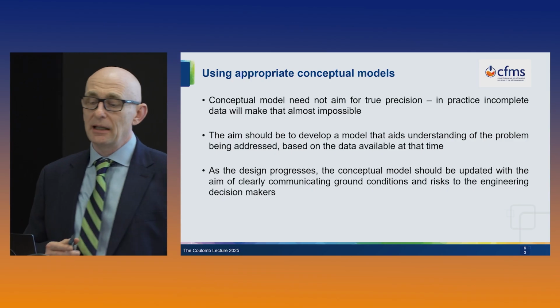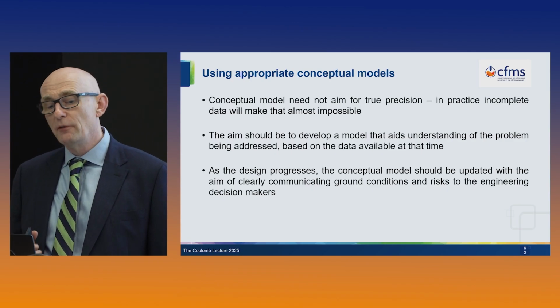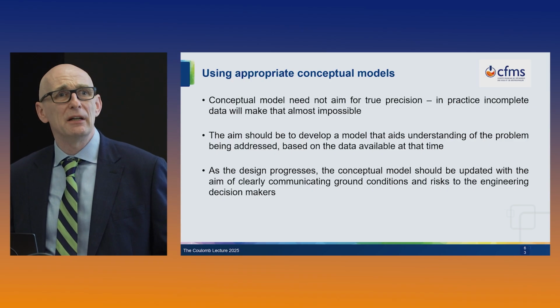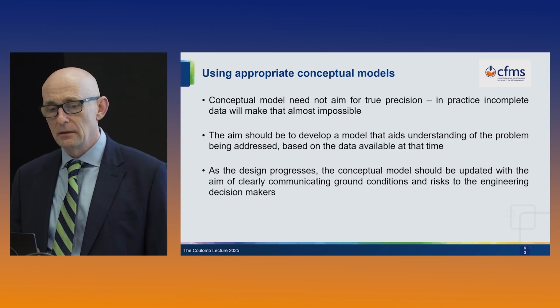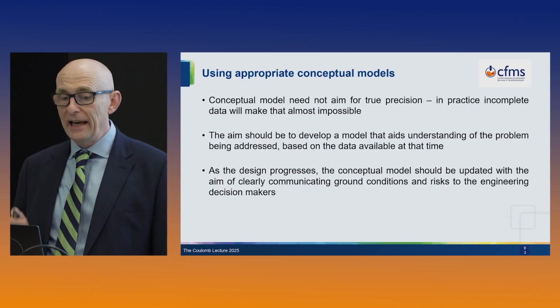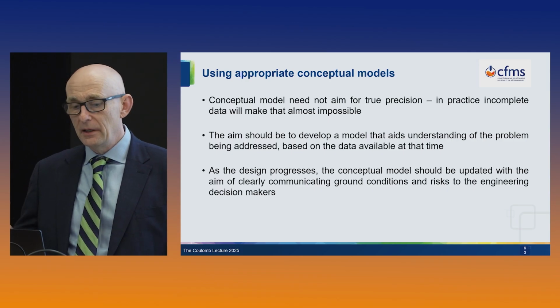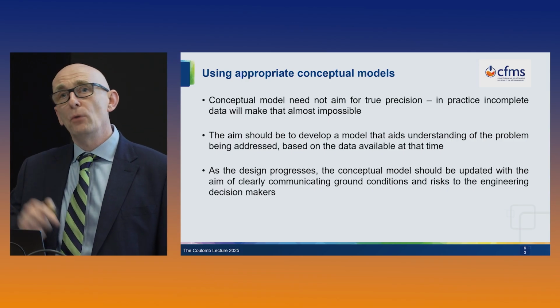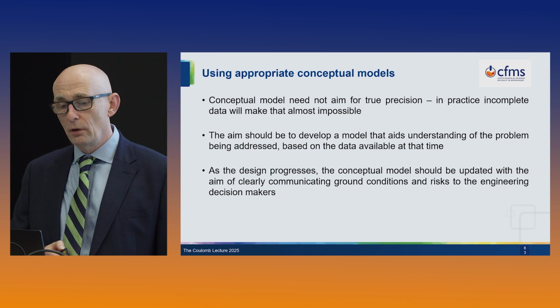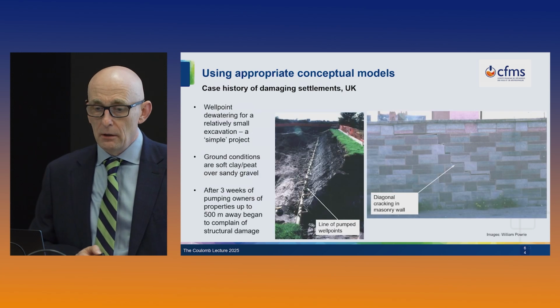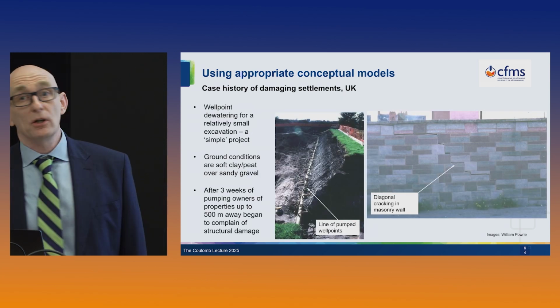And just like with seepage analysis, a conceptual model need not aim for true precision, and in practice you can't achieve that because the data will be incomplete. The aim should be to develop a model that aids the understanding of the problem being addressed based on the data available at that time. As the design progresses, more data comes in and you should evolve your model. So I want to illustrate this by means of a case study.